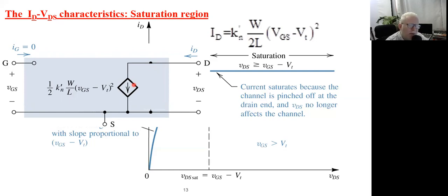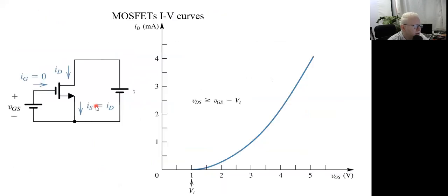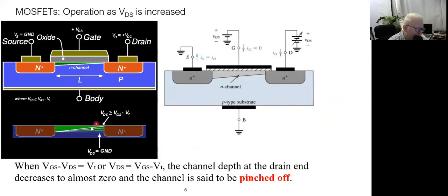There is a very important parameter here, which is again somewhat advanced. It may be somewhat out of the scope of this course, and most probably you will not use it until you reach year 4 and study the VLSI course, which is what we call the channel modulation. What is the channel modulation? Let me return back to this batch of slides. So this is the point at which a pinch off starts to appear, whenever the VDS is equal to VGS minus V threshold. Once you start to increase this VDS to be greater than VDS SAT, then what happens simply,